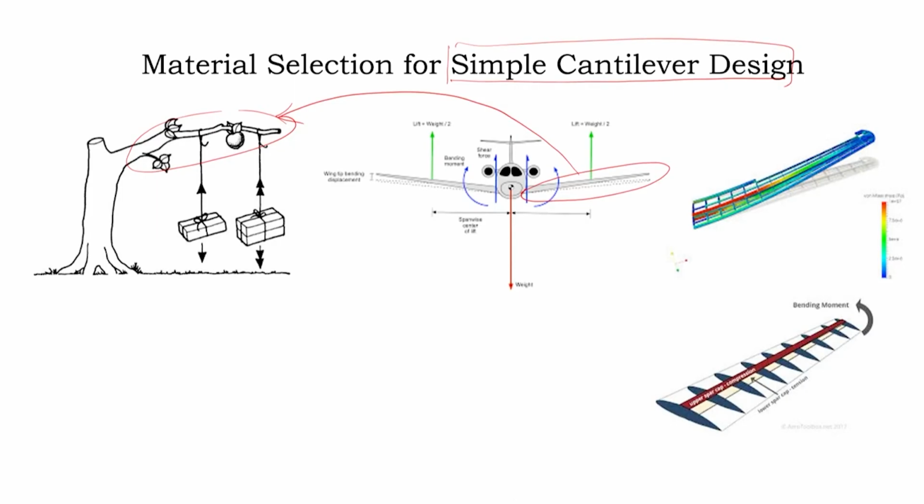Of course, there are many complexities there. For example, there is a main part, then there are spars which are used to maintain the shape of the aerofoil, and according to that shape you will get a variation of load. But at the core, these two resemble each other: they are essentially simple cantilever beams to begin with.